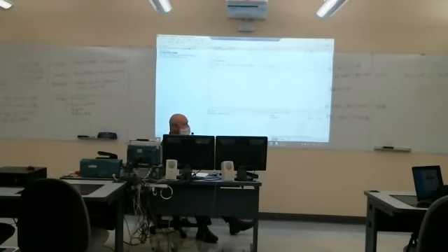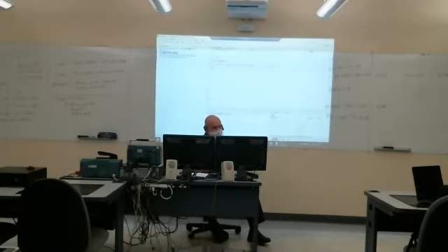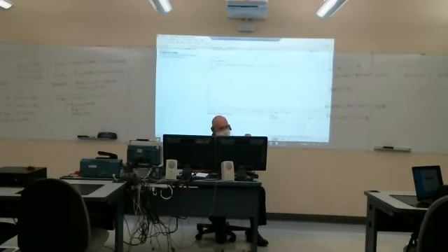It's got one line in it. The one line of code is to actually, our microcontroller has what's known as a watchdog timer on it. If it doesn't reset the watchdog timer, then your microcontroller reboots. Okay, so that's the guard against you running code that gets stuck in an infinite loop or something. We want to disable that, and that's what this line does. It does that for you automatically.